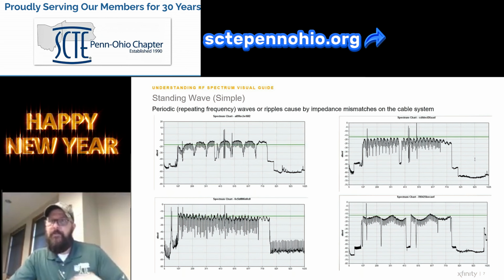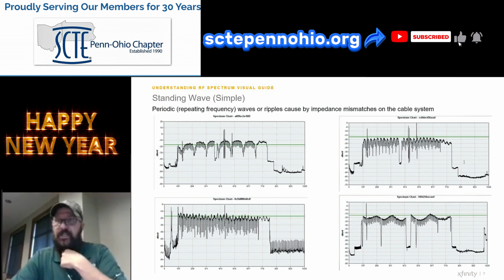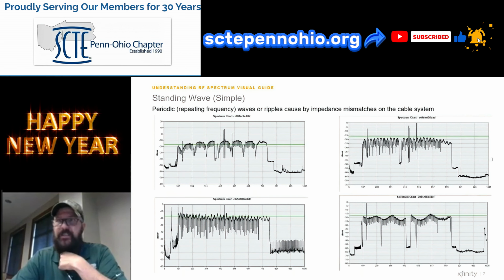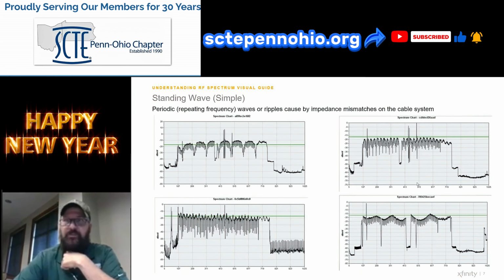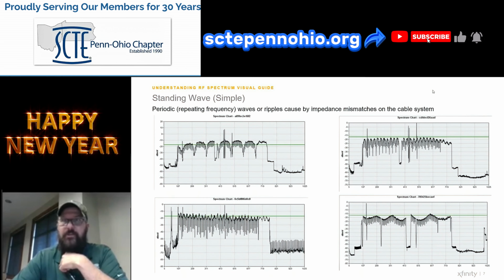Oh, thank you, John. The reference power is based on the resolution bandwidth, John says, going back to the previous slides. And to have a 17 dB correction factor, the cable must be using a resolution bandwidth of 100 kilohertz. Thank you, John.